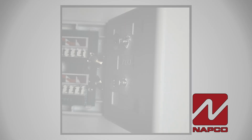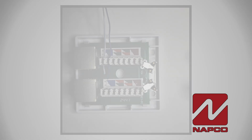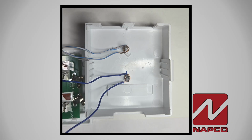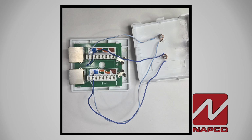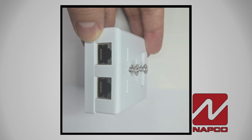can clamp onto them. Now, connect the wires for your blue and blue-white terminals on one jack, then wrap the exposed wire around each screw. Next, connect the blue and blue-white terminals to the other side. Finally, you can add some electrical tape or silicone to the screws to prevent them from shorting out on something. It will also help keep the wires in place. Now you have yourself a quick and easy RJ45 tap that you can use for troubleshooting. You can throw this in your tool bag or your truck and break it out whenever you need it.